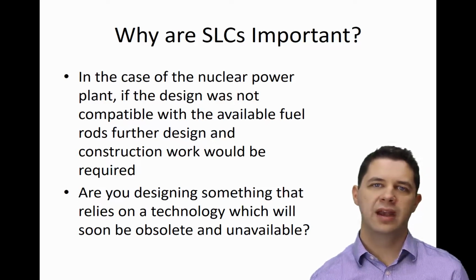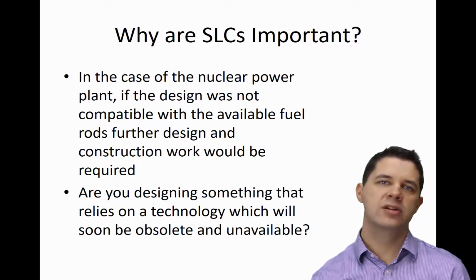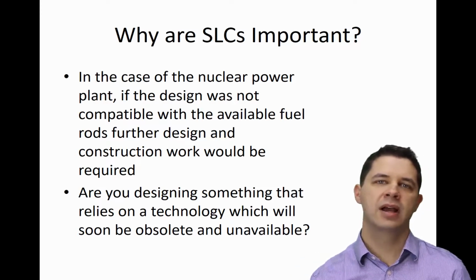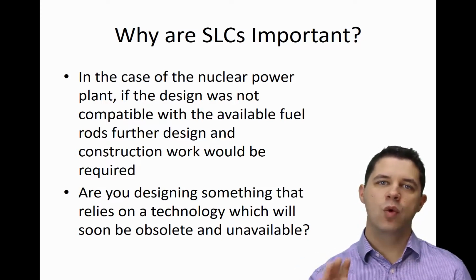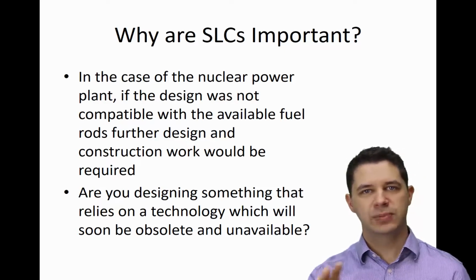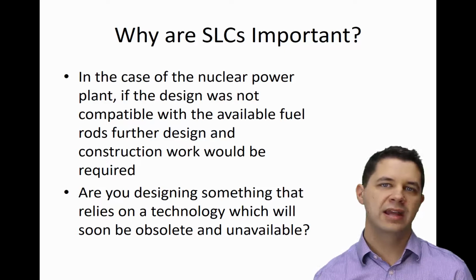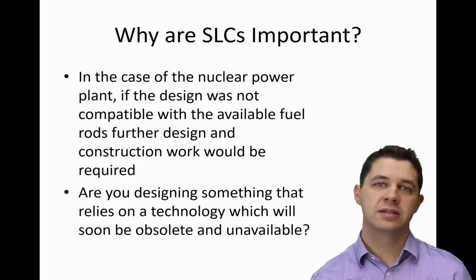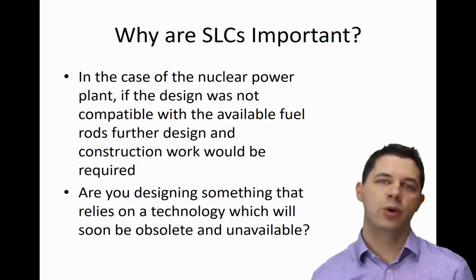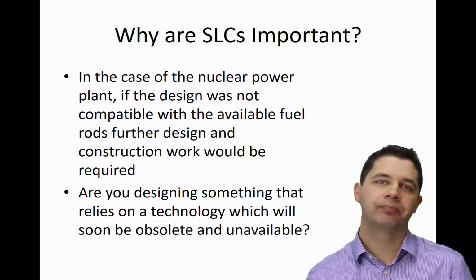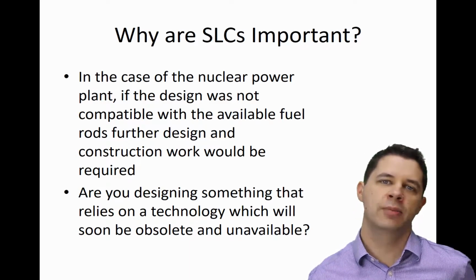And where we're doing electronics and using components and things, often we'll look on some of our websites, Element14 or something like that, and they'll give warnings saying this particular device will become obsolete in 2 years or in a year or something like that, or recommended not for new designs. That means we don't actually design it into our product that we'll be producing millions of things of, because we won't be able to buy it soon. We'll have to redesign our product sometime in the future.